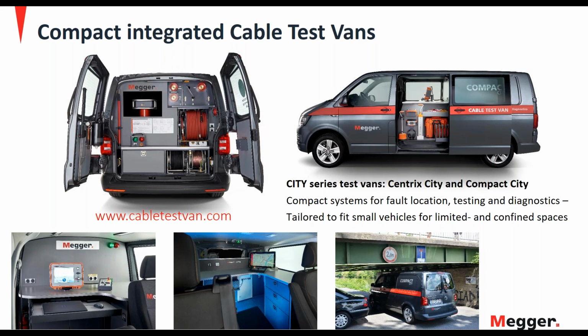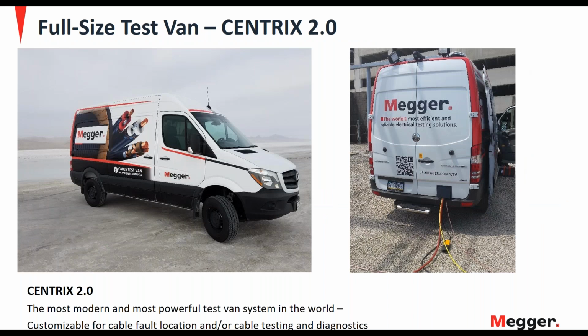The example that we're trying to show here is that you can have a completely integrated fault locating system inside of a small compact van. And here's another truck mount system, our Centrix 2. This is the most modern, most powerful test van system in existence. You can configure this a lot of different ways. Generally, this would have a full-blown fault locating system in it, as well as probably VLF, maybe tan delta, partially even a partial discharge test and diagnostics.